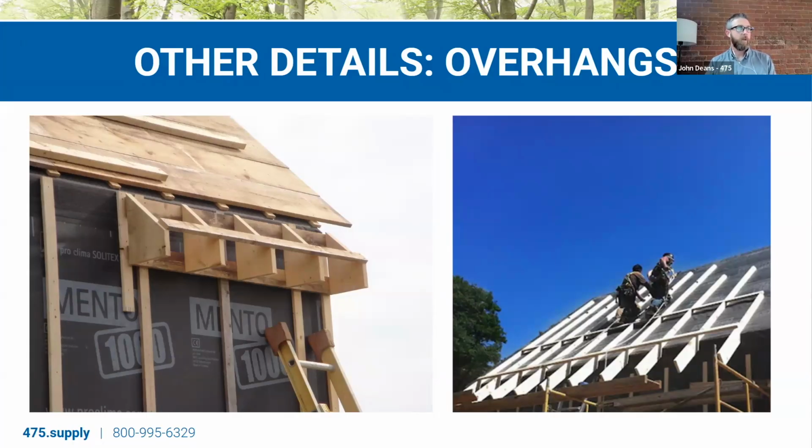So, we're looking at some other overhangs here. Same principle. We have that overhang built on the ground and then bolted up onto the side of the roof on the rain screen. So the rain screen is going up behind that and then coming out and can ventilate out the soffit if they're going to do it that way, or it can be connected with the roof ventilation as well. And then on the right, those battens, instead of stopping at the roof's edge and then bolting on an overhang, they just let them run long, and then they're putting 2x on the bottoms or the sides of them there to create the overhang profile so that it's all in plane with the roof. So a couple other approaches there.